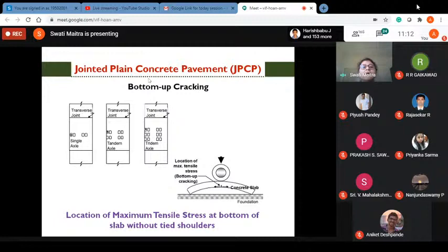Now, calculation of stress by finite element based analysis has been done, and IIT Slab 2 software has been developed to compute the flexural stresses. Of course, this finite element software is for a single slab, not considering the dowel bar or aggregate interlocking, but just for a single slab to calculate the stresses. And as we have seen, the critical locations are three: interior, corner, and edge.